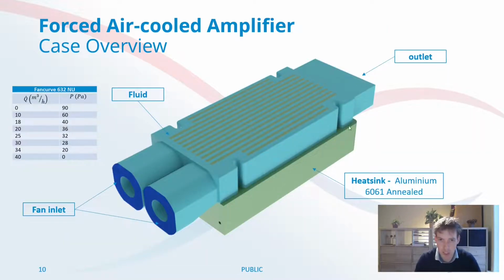So out of all these geometries, we have created the fluid region, and we start, let's say on left hand side, with 2 fan inlets. So again, in the step file that we have created, we have enclosed the volume of the fluid itself, and we have the inlet and outlet surfaces included into the model.